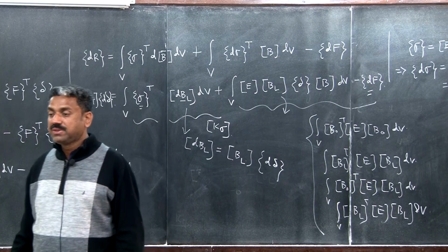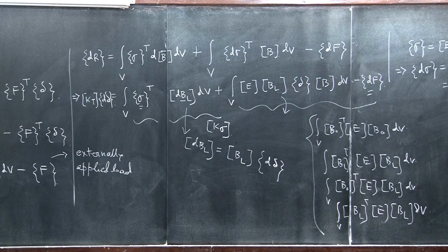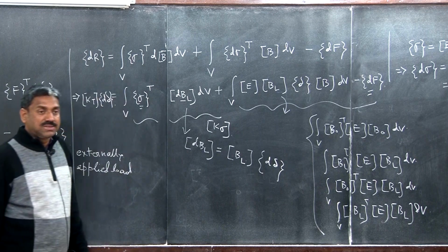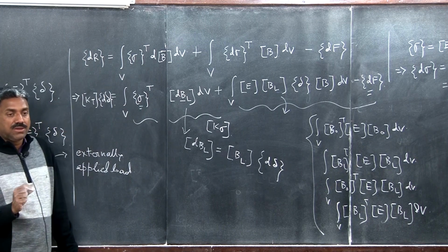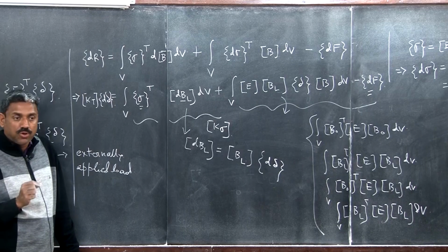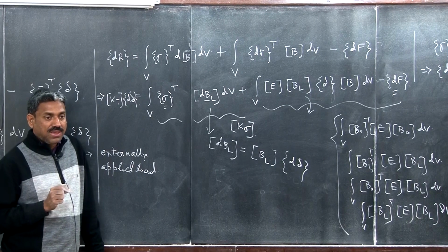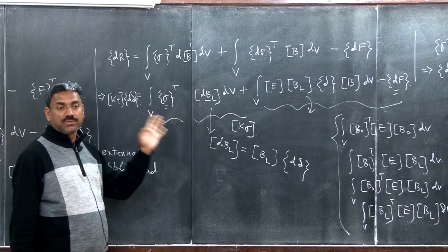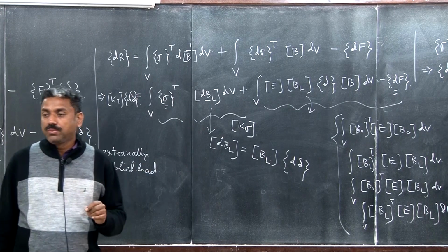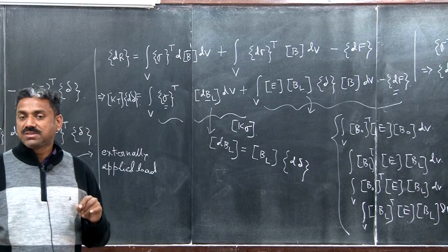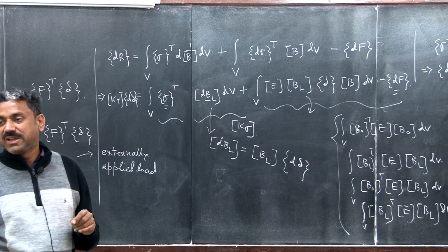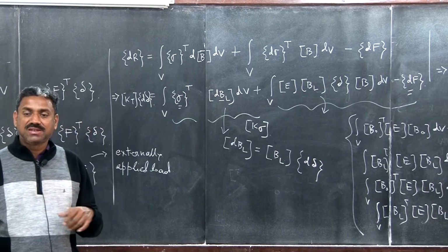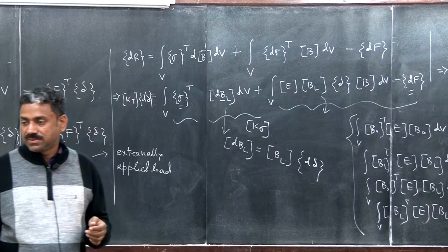What is important to see here is that when we do the nonlinear analysis, the geometric stiffness matrix plays an important role, okay. The point I wanted to make here is that the geometric stiffness matrix becomes a part of the tangent stiffness matrix for nonlinear analysis, but it is not everything. There will be additional stuff other than the geometric stiffness matrix, okay.